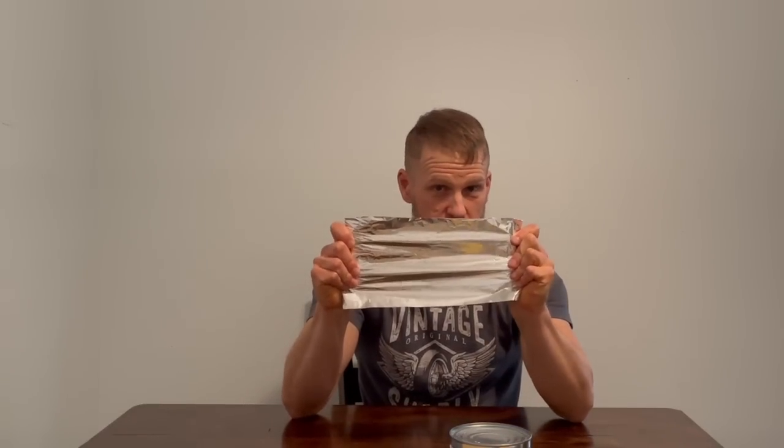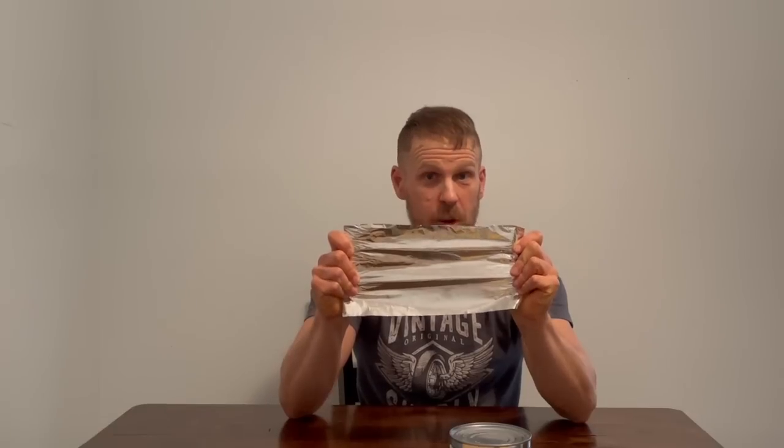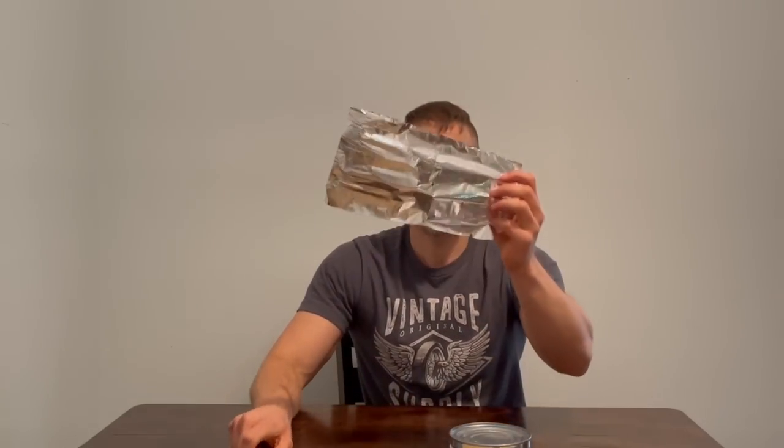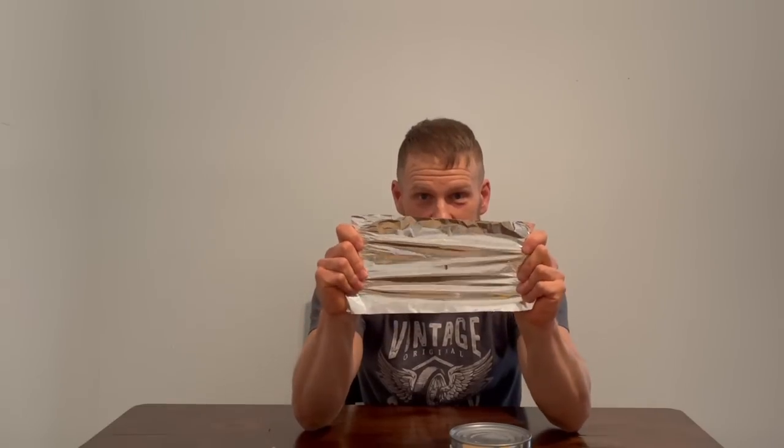It happens in all kinds of materials. Here's a piece of aluminum foil, and without any hole in it, you can pull on it quite hard and it will not separate. Now, if I take a knife and just poke a small hole in it, now if I pull on it, it doesn't take much force for that hole to create a crack, and then it splits right through that crack.